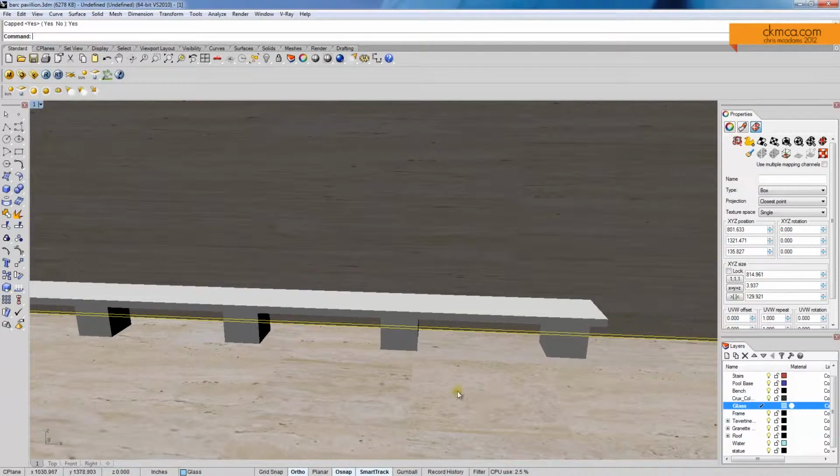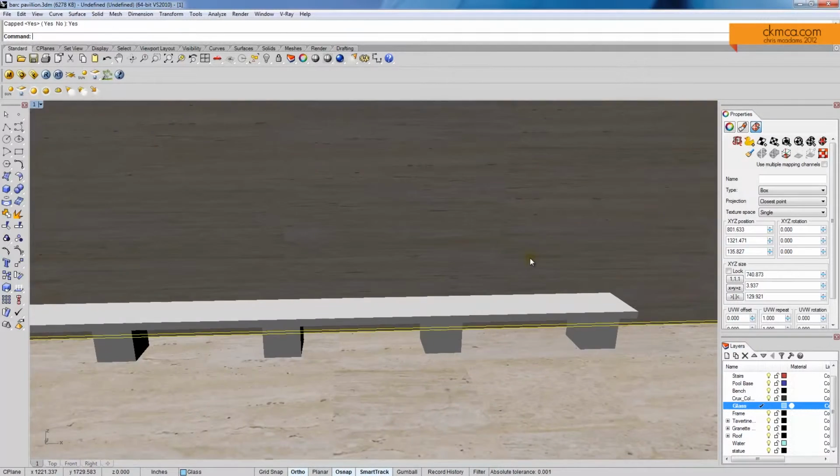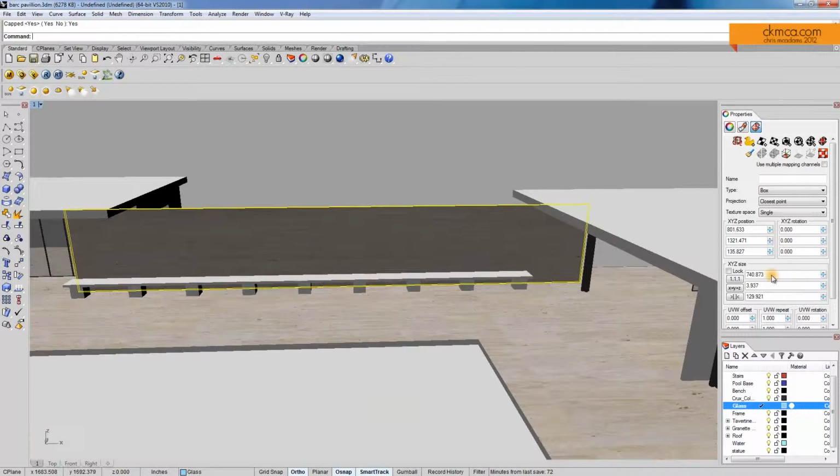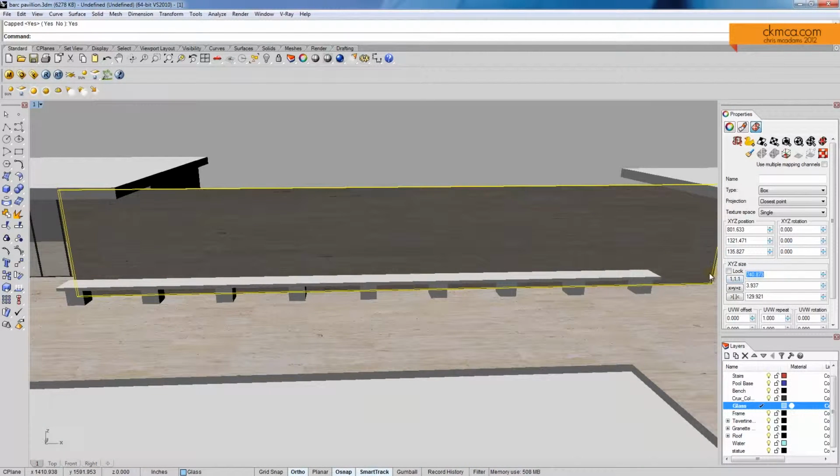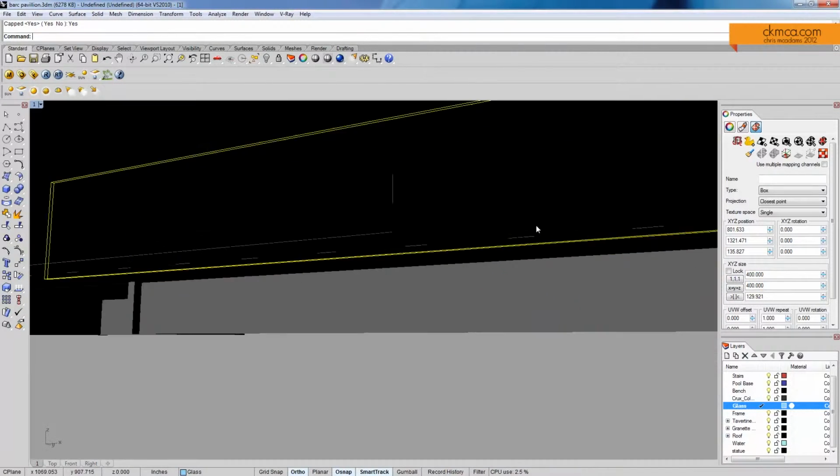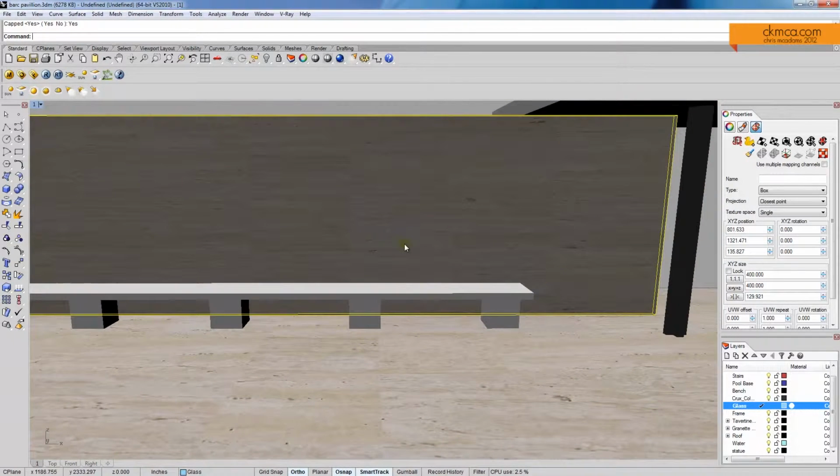to scale this to match exactly what the floor is. So here it's at 800, and it's at 800 because the total length of this wall matches that. I'm going to drop this down to say 400, and we'll do this one 400. And although the X position looks right, the Y is definitely not. So we're going to have to change this maybe to 40. There we go. It's going to be the Z that controls the number. Let's go 1. Too many, so 400.